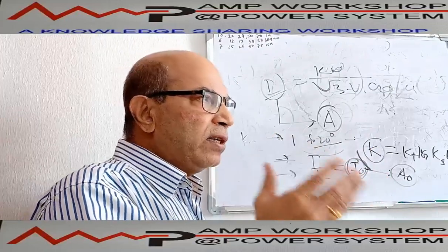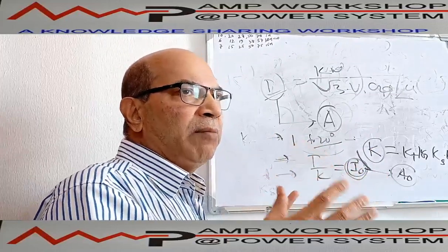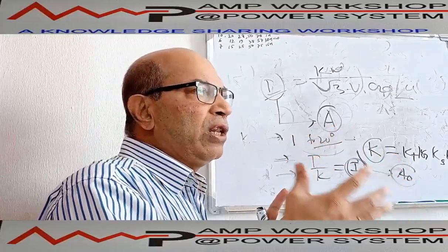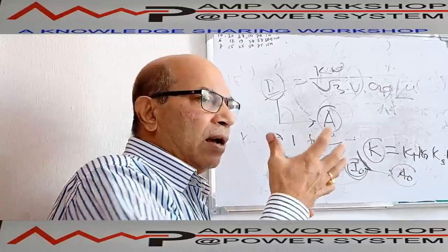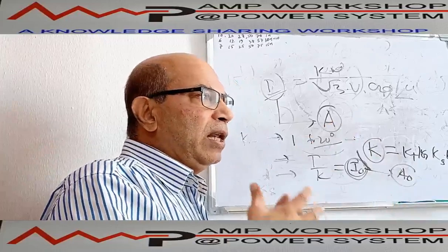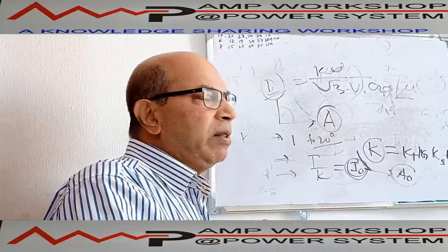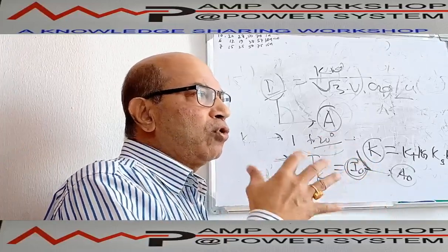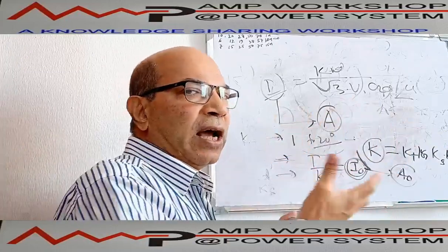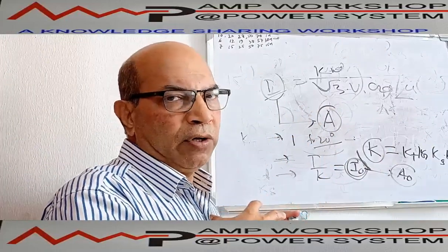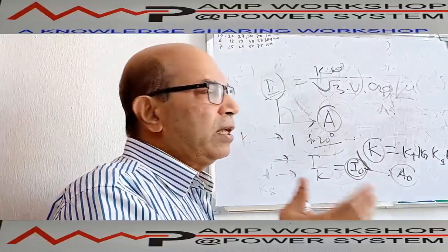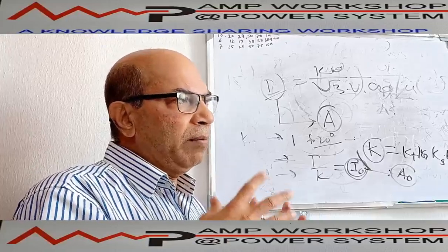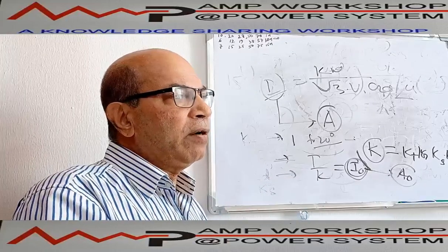So at what stage are you deciding the cable? If the cable is already in your hand and you want to install it, then you use the cable catalog. But if you are deciding the cable initially, before ordering, then you use IEC. Or if you have planned 3-4 contractors, then you should tell them to calculate all this accordingly and come back to you. Okay, so this way we can estimate the cable. That is all about cable sizing for our daily requirement.